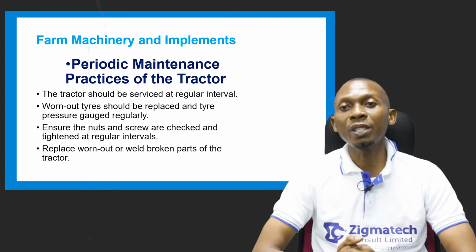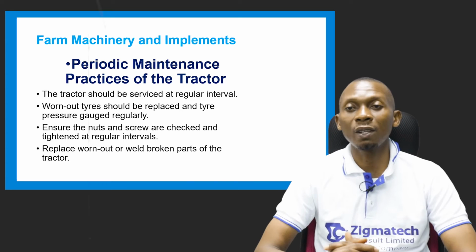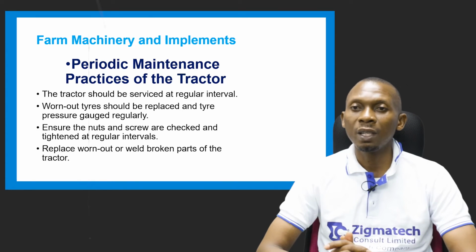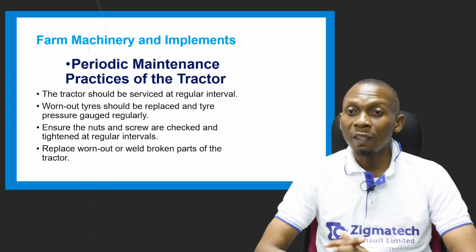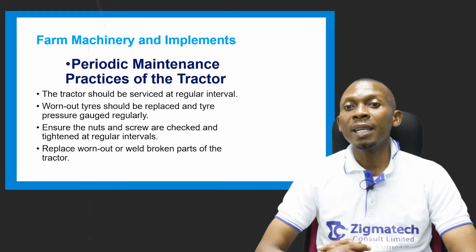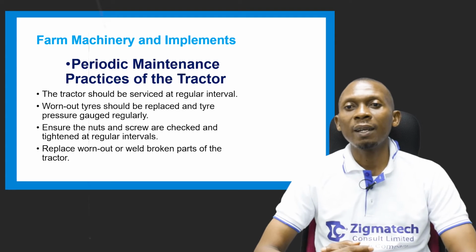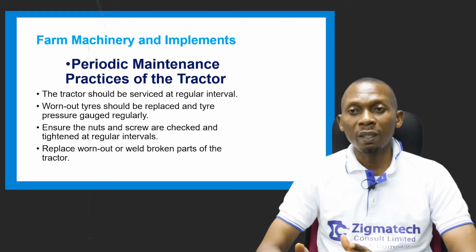Now let's look at the periodic maintenance practices of tractors. Not what you do daily, but what you do at regular intervals. Now, we have to service the tractor at regular intervals. That has to do with changing of the oils, checking of the plugs. Now, this has to be done at regular intervals.